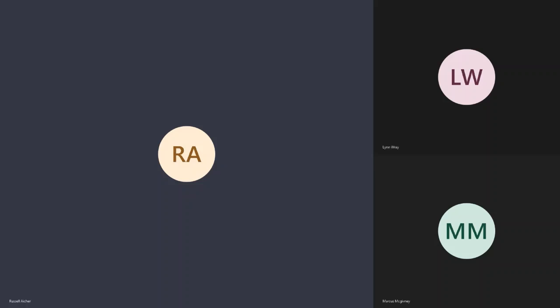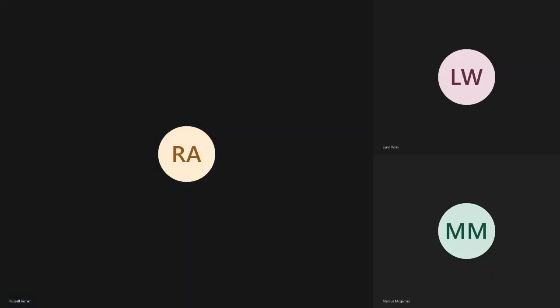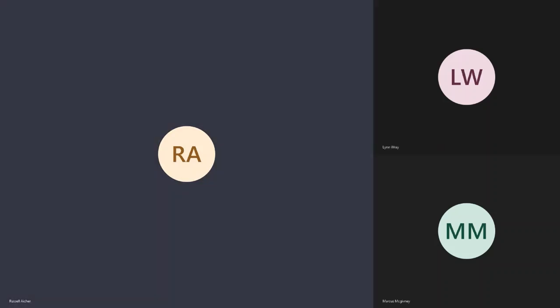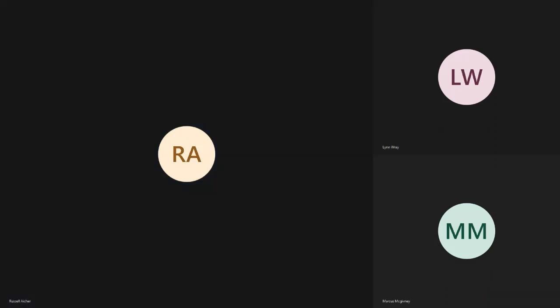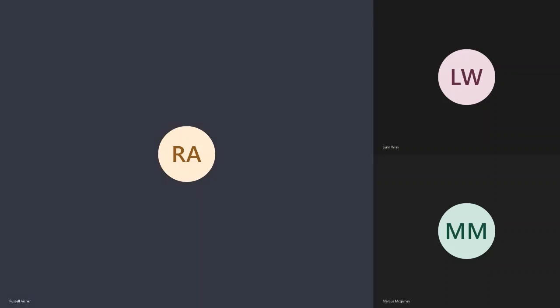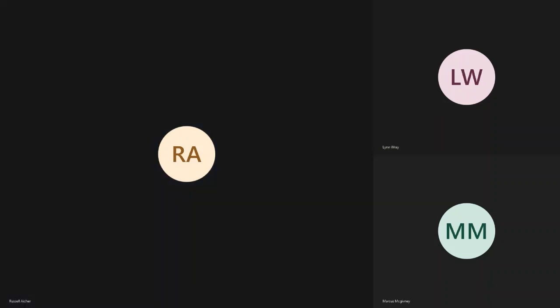You start digitizing a line. The first time you click to start a line, you've created a node. And then you start tracing something. Now you're entering vertices. When you double click to end that line, you're entering the second node. So a line can only have 2 nodes, except for, we'll come back to the exception. And then the vertices in between give it shape. If I don't have any vertices, what do I have? I just have a node, a start node, and an end node. I got a straight line.